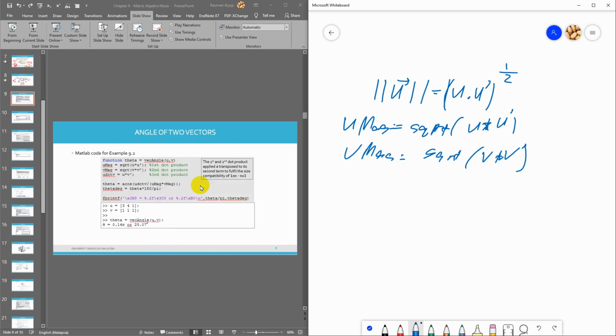And then this one in degree. Basically, whatever cos or sine you use in MATLAB uses radian, so be careful: not degree but radian. Anything you calculate in MATLAB using the cos function is in radian. If you want to use degree, you have to use different code. I forget the name, but I think cosd, tand, something like that.